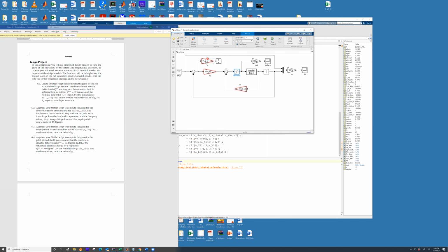So now the only thing that should be highlighted in your Simulink block is Kp and Ki. So how do you tune this? There are two ways to do this. We can actually go back to the rules that are given to us. For example, Kp is given as omega n squared divided by a phi 2.